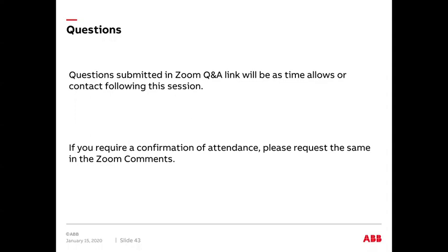Okay, so if you look at HART communication, Modbus communication, and these types of communications being mentioned, these are industry standards. ABB offers those, and a lot of other suppliers do, and they're all supposed to follow industry standard communication protocol. That's one thing that ABB really strives to do. These are digital communication profiles. So you have a transmitter that's sending that type of digital signal, and you have a receiver that's receiving and interpreting that digital signal. So they're just digital signals, and ABB believes in a very open architecture. So our transmitters will send that industry standard signal to whatever device you have, whatever you need to do as far as reading that signal.